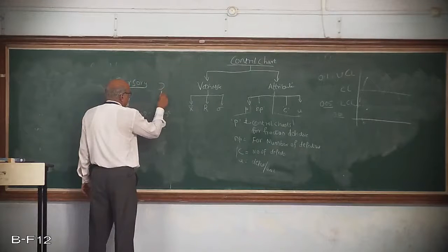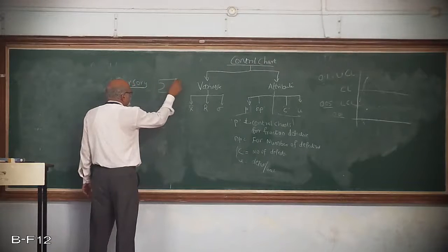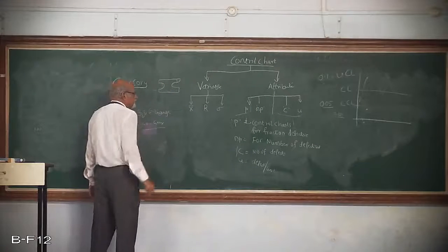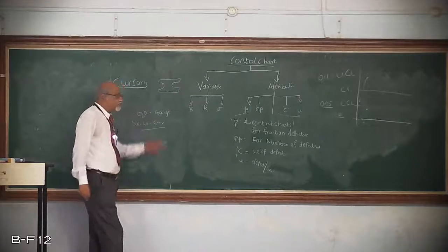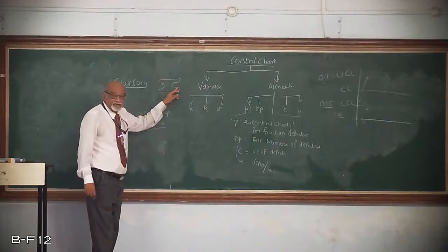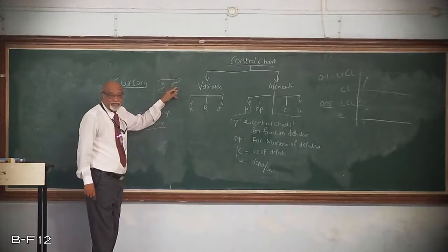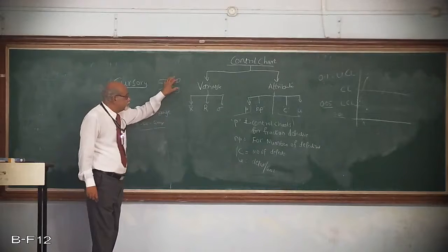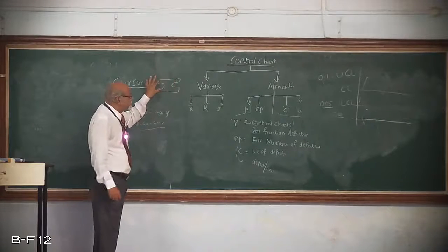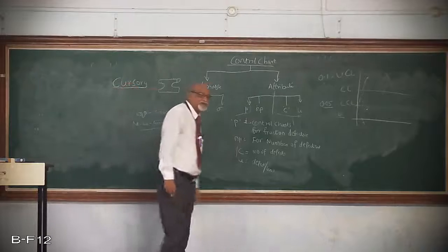The go gauge will be like this, go gauge and no go gauge. This side if I put it, the go gauge should enter. No go gauge means it should not enter. So it is based on the smaller dimension, minimum material, and this is maximum material. That's as simple as that, outside diameter.